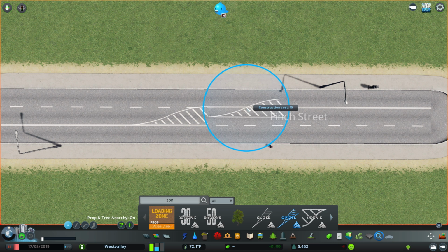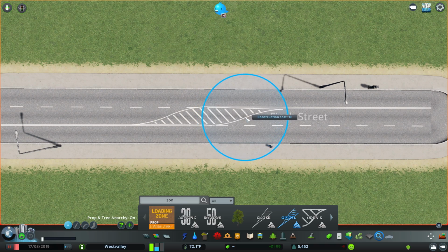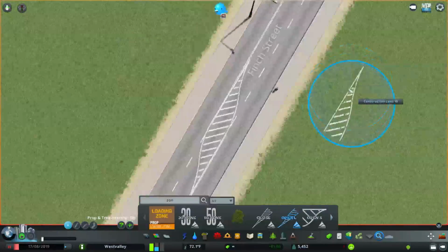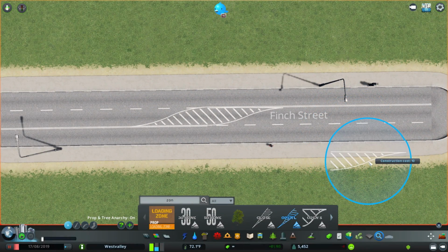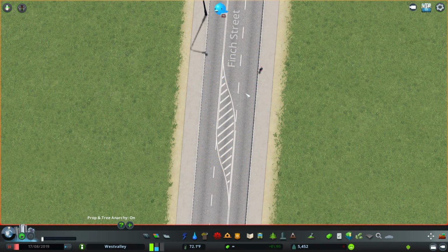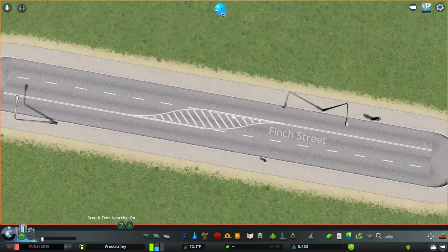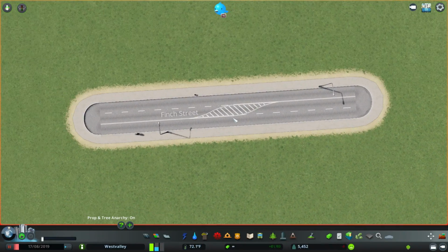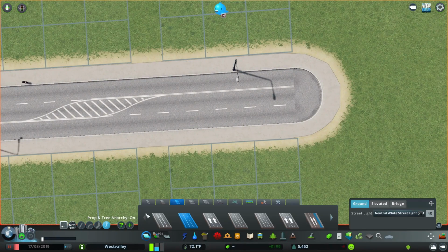I'm going to use the same decal here and rotate it with my mouse button. Place it down like that. If the decal is slightly misaligned, I can also just use Move It after the fact and realign it so it looks more aligned like this. So once this looks good, what you next want to do is make some cross streets.